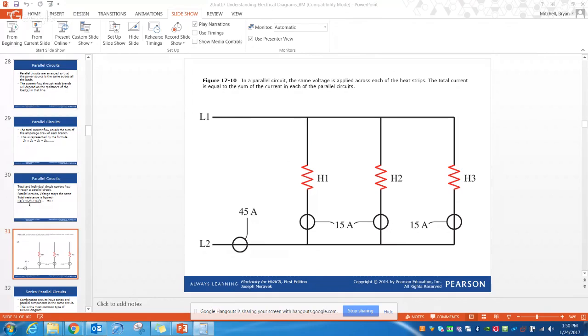That's a great example. And one of these heaters, they all should be equal, because you're expecting to put equal heat out of every one of them. But one heater's drawing 20 amps, one's drawing 8 amps, and the other's drawing 12. So you can tell, oh geez, I have some stuff happening inside of my elements here. So everybody got that? Good enough to move on?